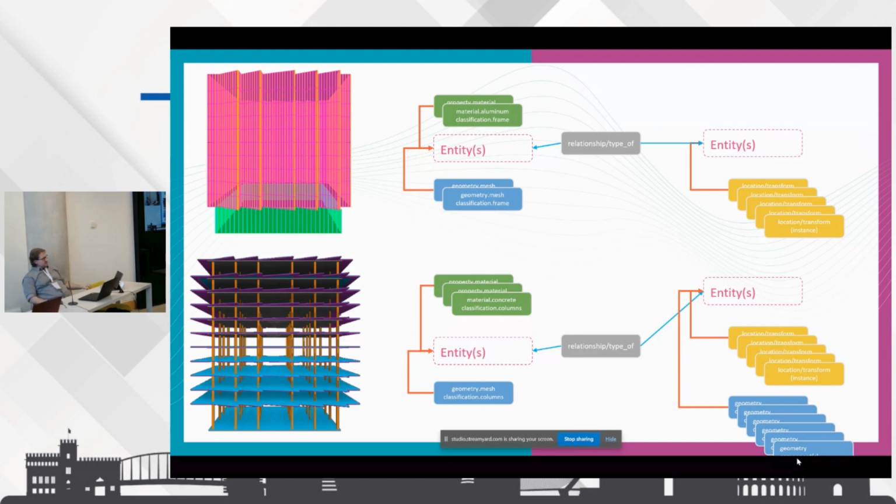So, as buildingSMART, we probably have to put more in the data than you would if you were building the tool. So I think the discussion is really around how do we represent versions? Do we just come up with a common hashing procedure to say a hash represents the uniqueness, or do we need a component ID, entity ID, and component version that has its own ID versus a hash? That's the discussion I think that's happening right now.